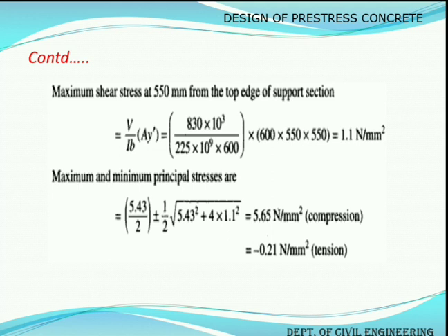That means as we don't have any vertical prestressing in this case, we find that there is a tensile stress existing, which will result in shear cracks. Okay, so we find that here we have to resist this tensile force. So this ends the analysis examples. In the further examples, we will be going with the design for shear. Thank you.